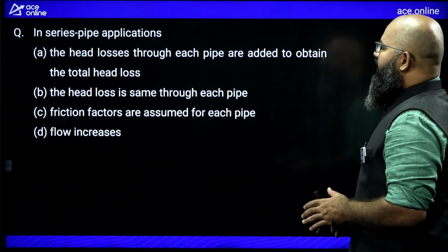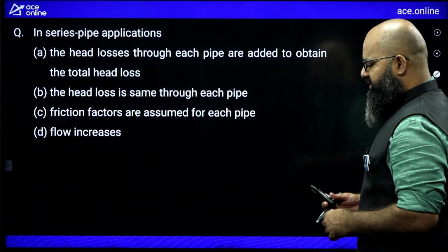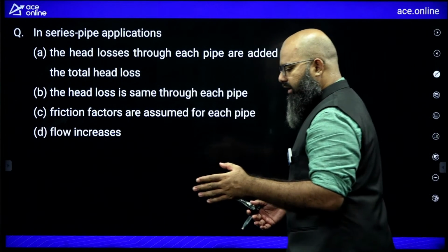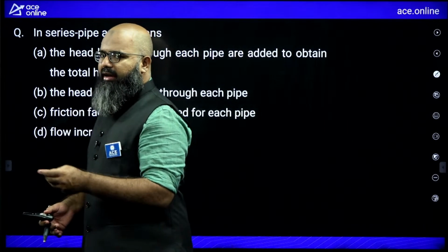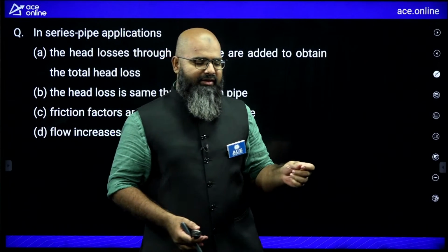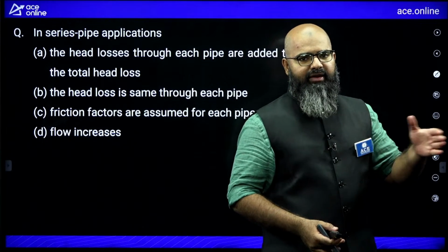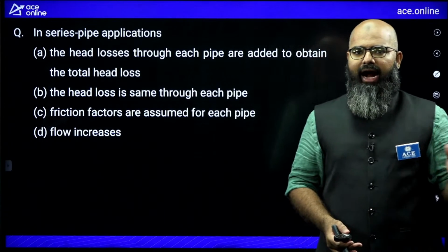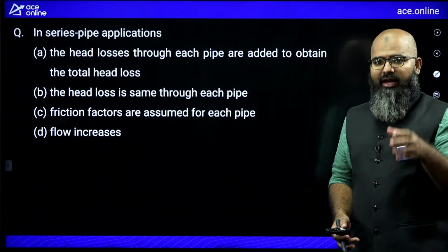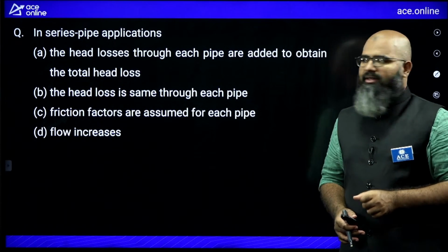Moving further, in a series pipe application, you are having two types of arrangements. One is series, other is parallel. I hope you remember in the case of series arrangement, the discharge everywhere is going to be same. The head loss is supposed to be added up. In the case of parallel, discharge is added up and the head loss is going to be same.